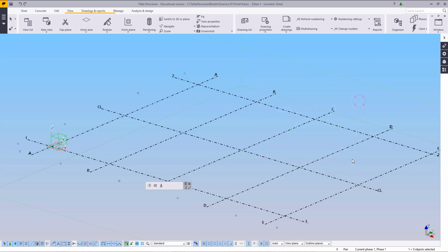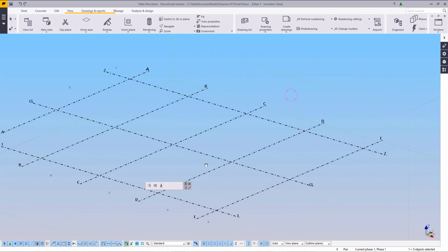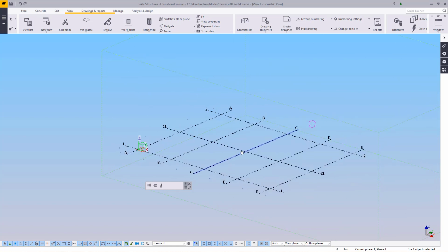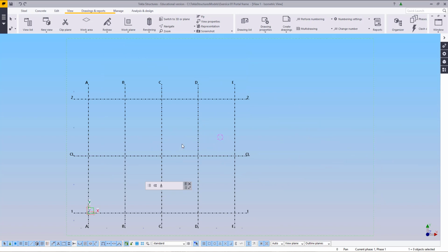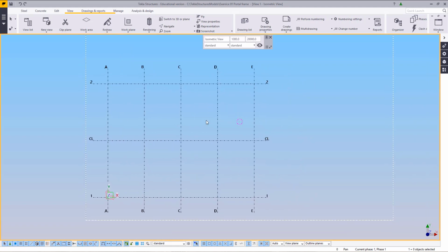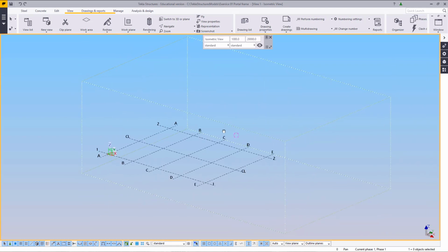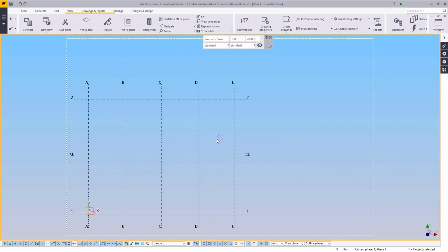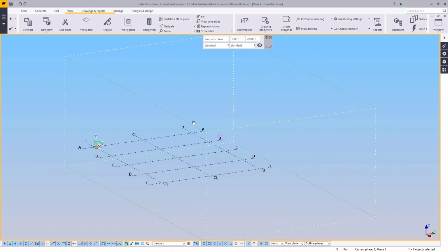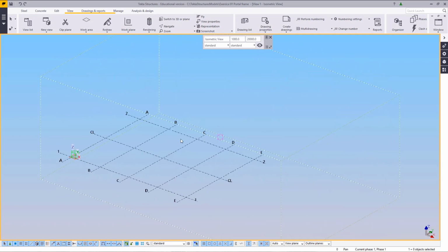Now, when you're starting off on Tekla, it gives you this 3D view to work from. You can get a direct view on your grid by simply pressing Ctrl P to get a direct top view. Let's just move this up there somewhere, and Ctrl P, get back to 3D. Also, you can hold Ctrl in and hold down your middle mouse button in order to rotate it around.